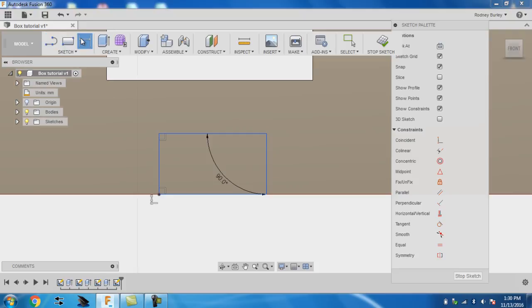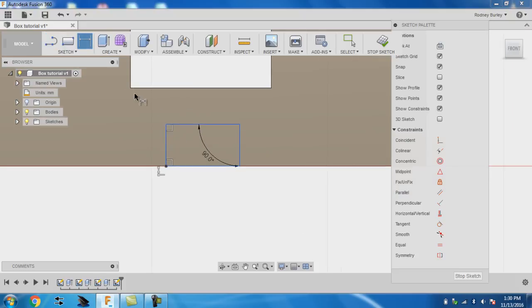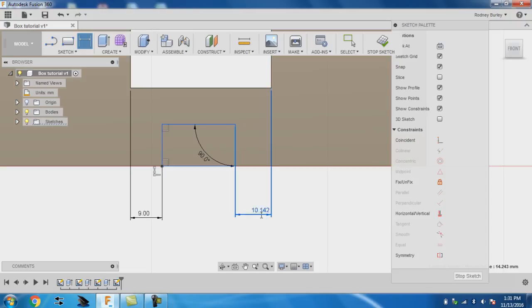Now click this key and we're going to do some dimensioning from here to here. That's going to be 9 millimeters. And from here to here, it's going to be 9 millimeters. So that'll automatically make this 22, I believe. Then we're going to click on from this to this, to there, to there. From there to there, to make that 15 millimeters high.